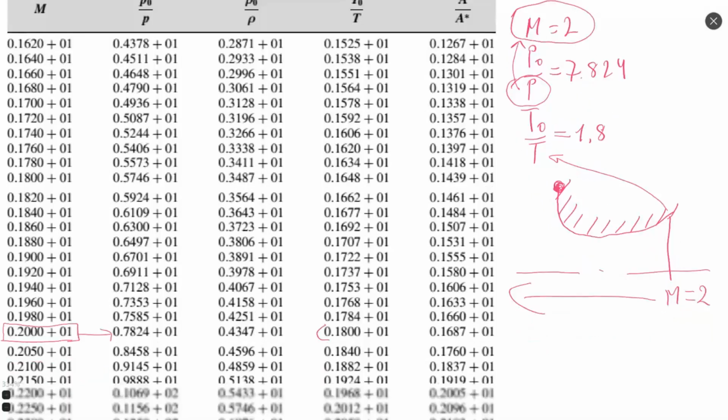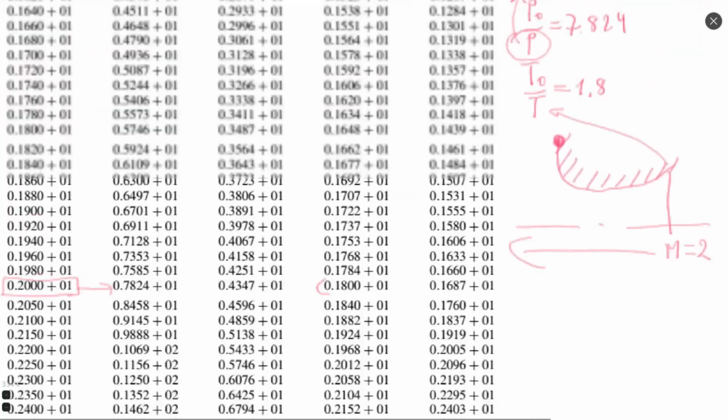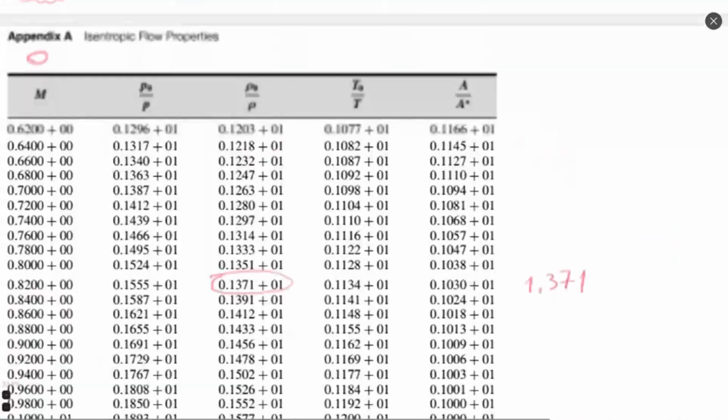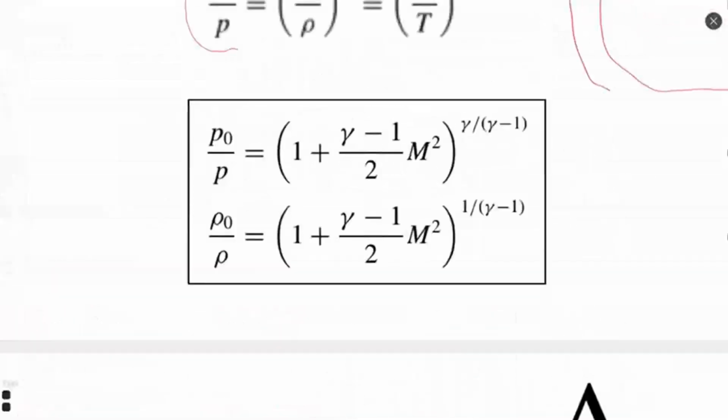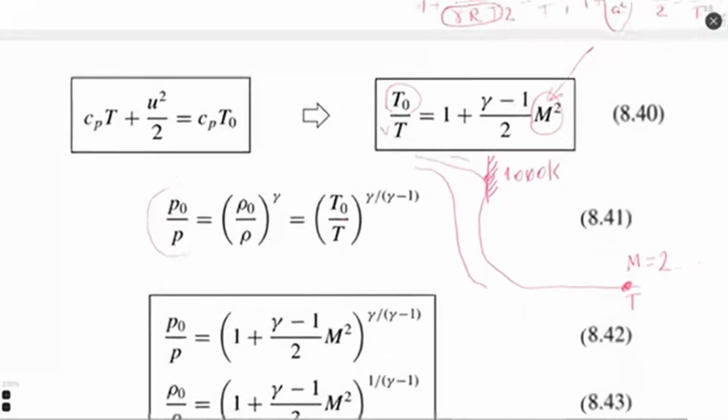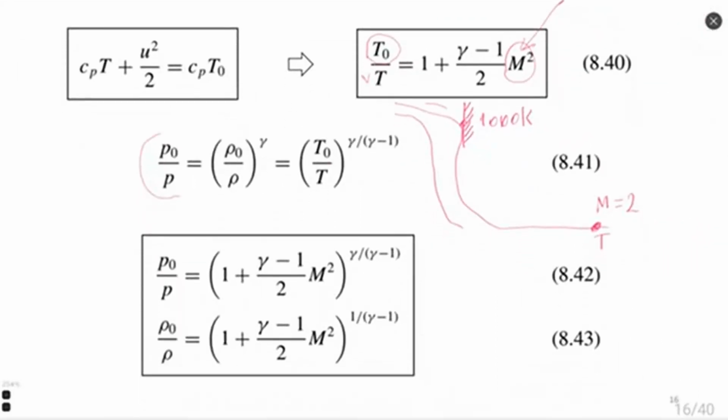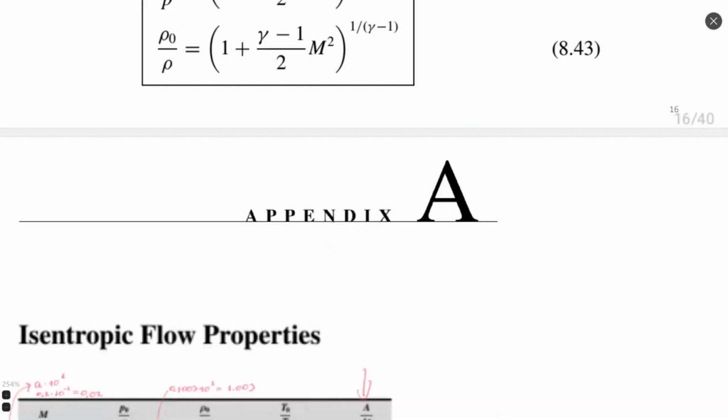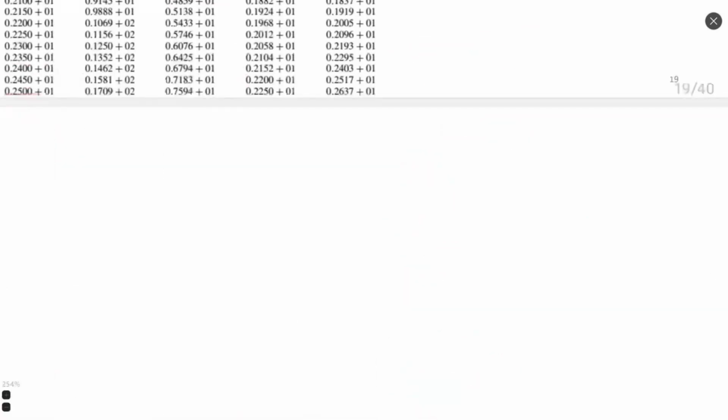We will see them. So this is the next one, appendix 1, allowing us to not calculate using these isentropic relations, but to just choose values from the table quite fast, rapidly, in the direction from Mach to thermodynamic properties, and vice versa from thermodynamic properties to Mach number. So it can go both ways. Okay, that's it.